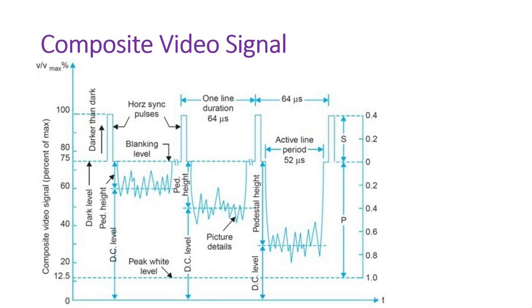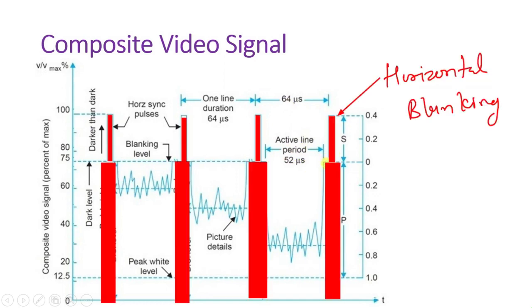Camera signal amplitude: the white peak is approximately close to 100 IRE units. However, the black setup is 7.5 units to offset the black from the blanking level. By subtracting the black setup from the peak white, the result is 100 minus 7.5 equals 92.5 IRE units for camera signal variation. This number is 66% of the total 140 IRE units.